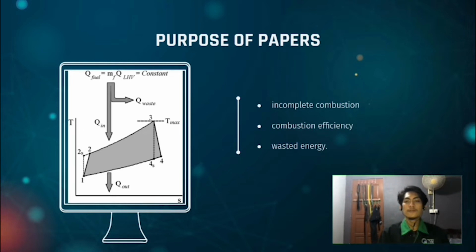As shown in this figure, it is assumed that the mass of fuel supplied to the engine per cycle is fixed. A fraction of the fuel's chemical energy, which is Q, can be transferred into the working fluid, and the remaining part of the fuel energy cannot be utilized and is considered waste. This paper studies an Otto cycle model with its irreversibility originating exclusively from the expansion and compression process.